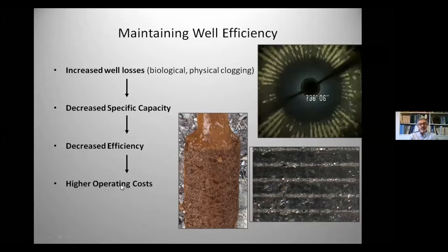You can also check your electrical costs and see if they're going up, because now you're having to lift the same amount of water over a higher lift. So these are some of the symptoms you'll see if you allow the intake structures to be impacted by issues such as mineralization, sand clogging, and bacteria.